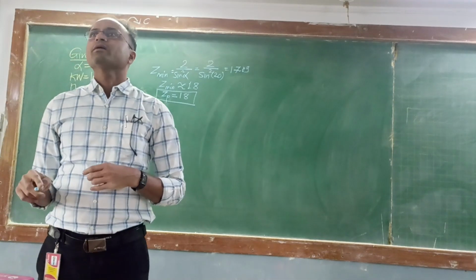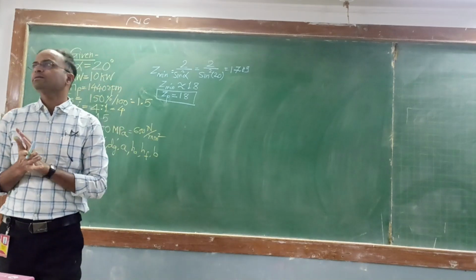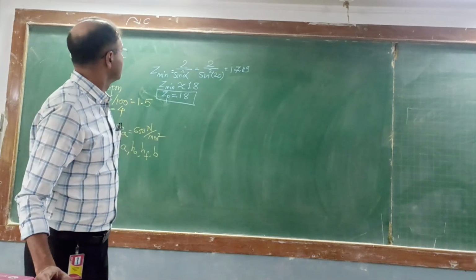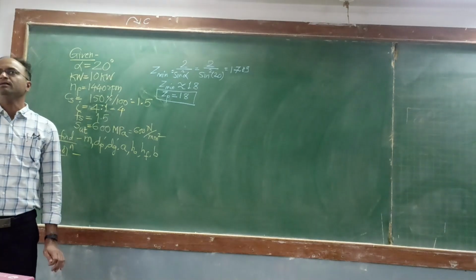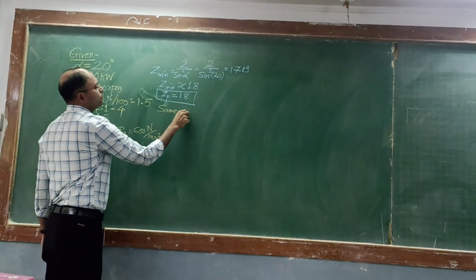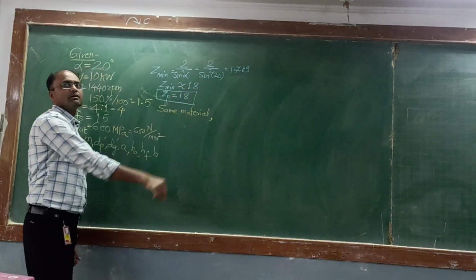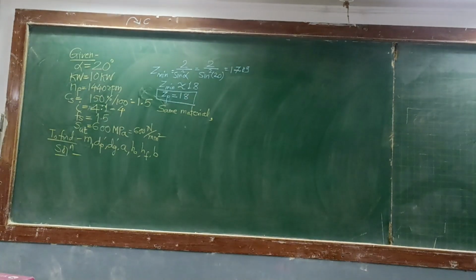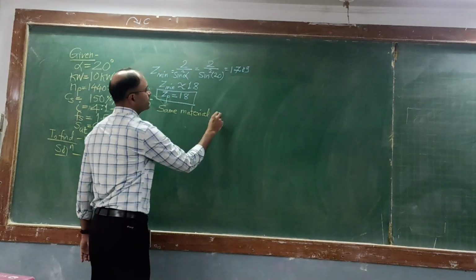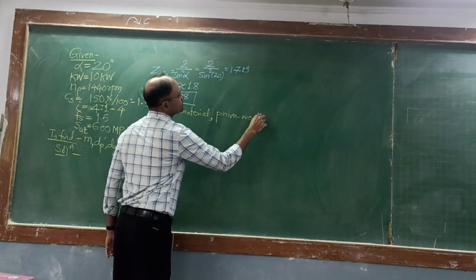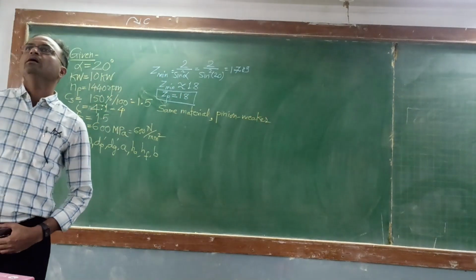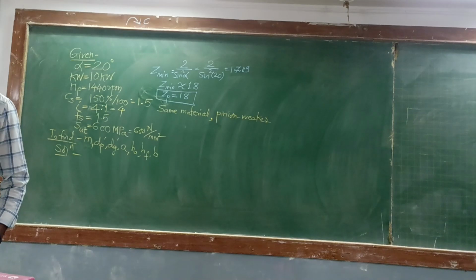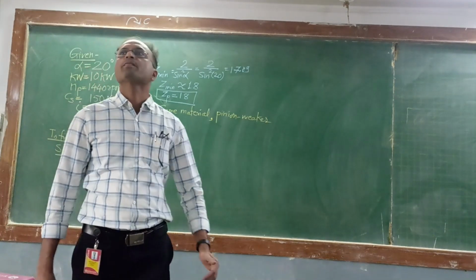Write out the next statement: when pinion and gear are made of same material, pinion is always weaker, and hence design is based on pinion.